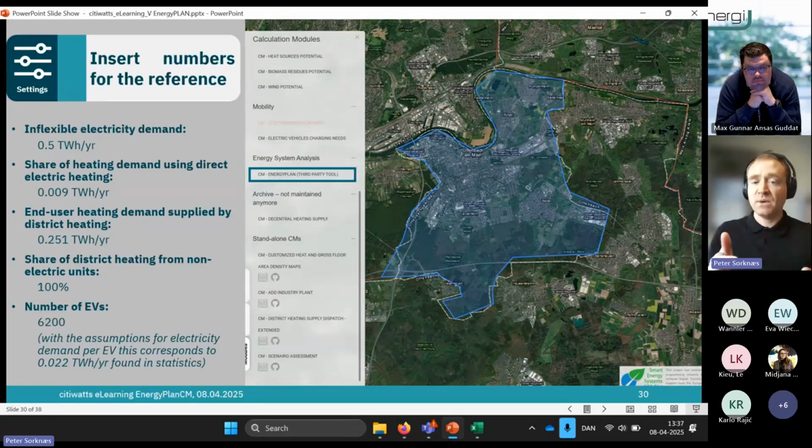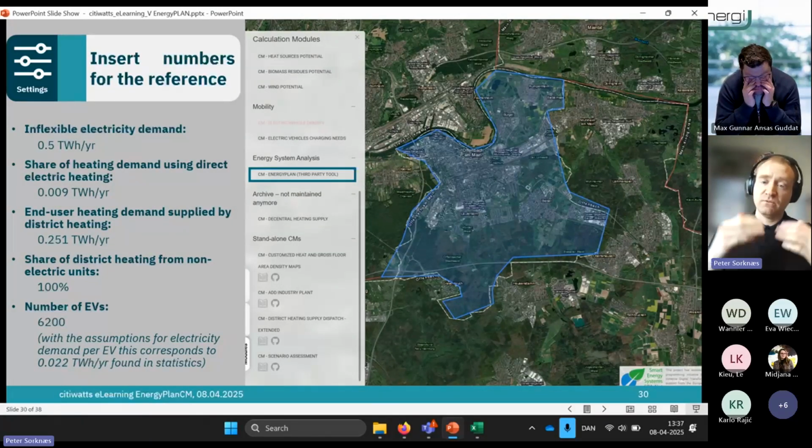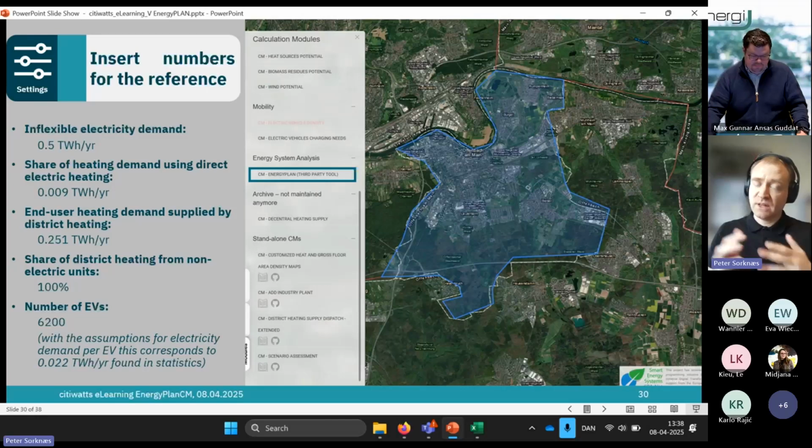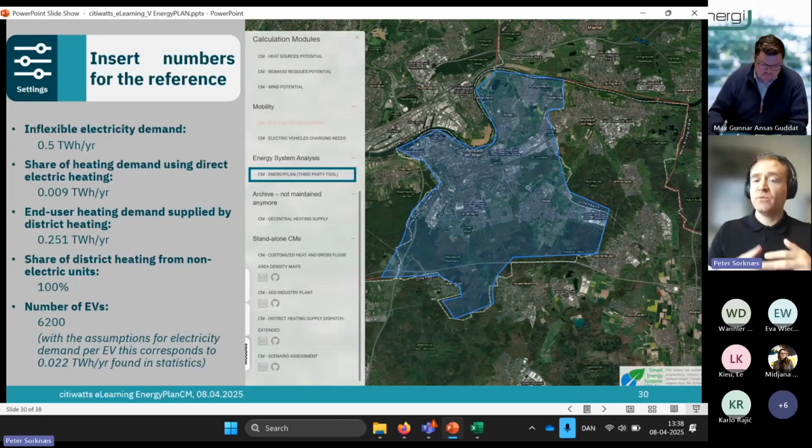If you add PV panels and wind turbines, the tool will try to make sure that the heat demand is sufficiently maintained using local storage facilities in the building areas, something you can define yourself, to move that load of electricity, so move when it actually consumes electricity to provide the heating. If you set 0 storage, that means it's inflexible. If you add a storage for heating in the buildings, it will be able to move it around. And that actually means that we can use more wind power and PV locally.